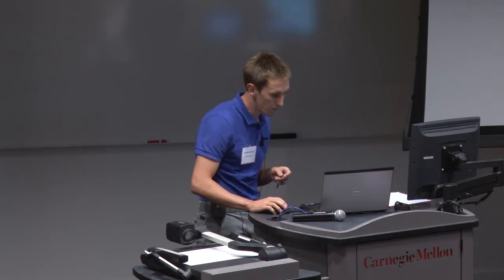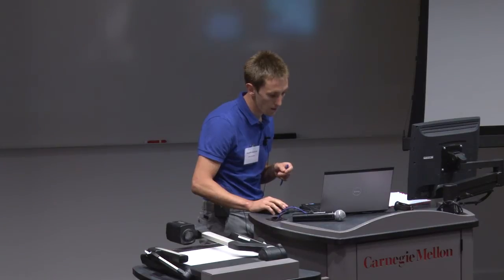Okay, just to make sure I understand it. Did you compare the amount of energy you put in from the muscle versus the improvement in metabolic cost? And for this one, you took the approximation from force times velocity from the muscle, or where did you take it exactly from? We measured the force with a load cell, and we measured the ankle angular velocity with 2D video kinematics. We multiplied both so that you obtain power, and then integrate it, and that gives you the amount of work.